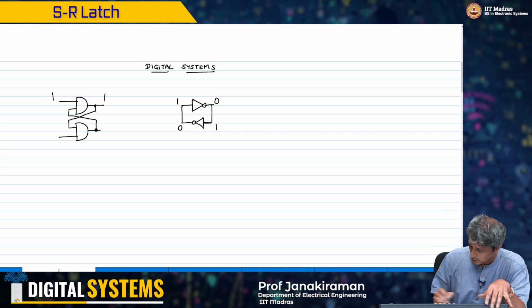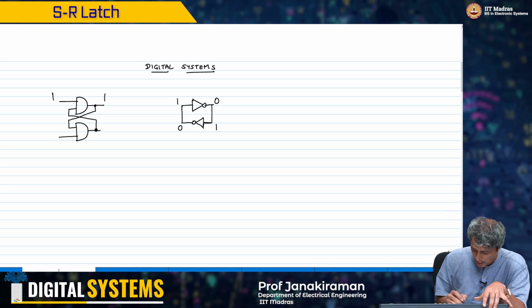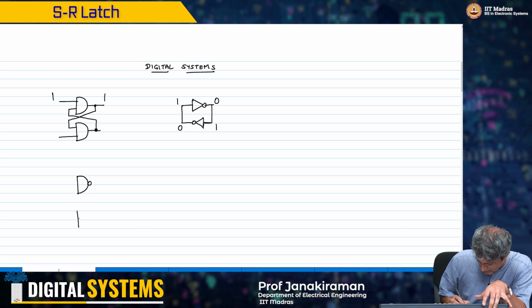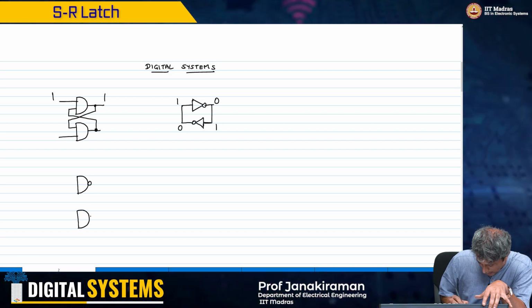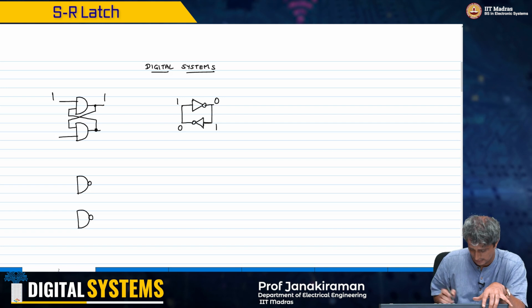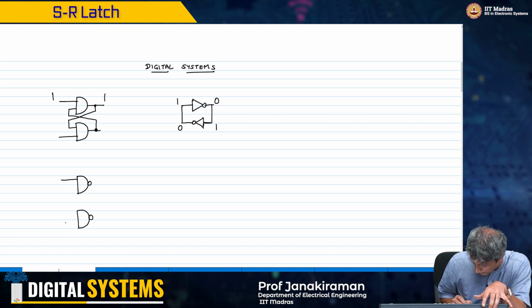That's why you will see that any alternate structure of the latches will either be done with NAND gates or NOR gates. Of course, like inverters, you need that inverting gate in order to hold the state. So let us analyze this structure now.